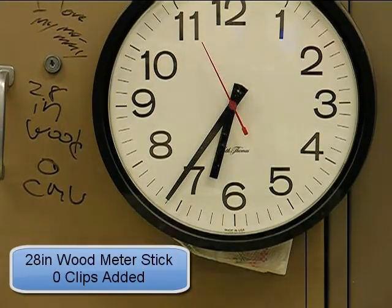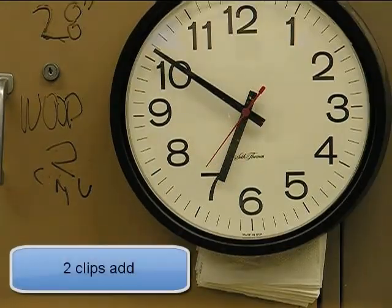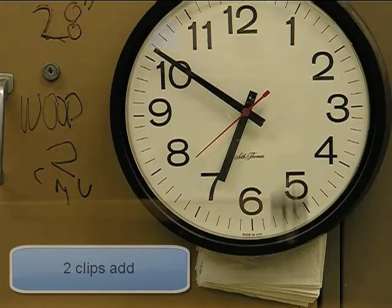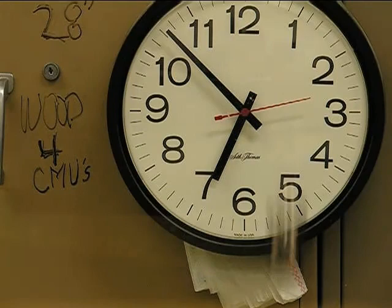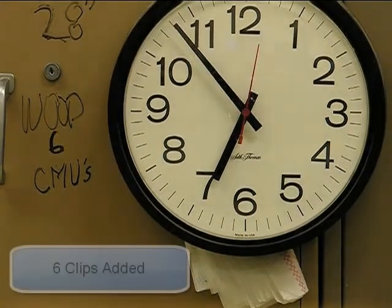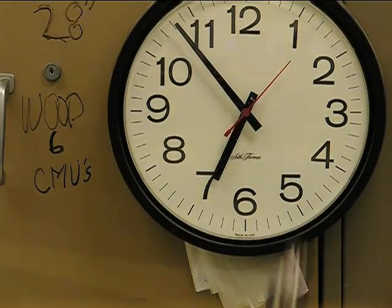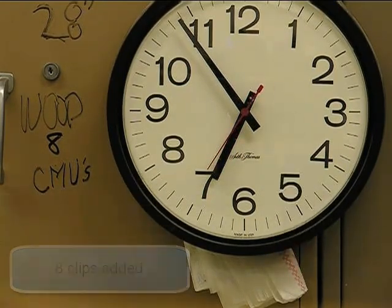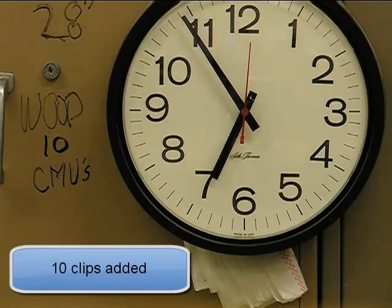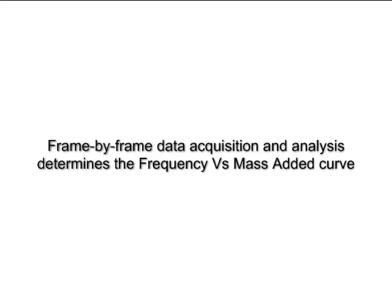So here you have 28 inches of a classical wood meter stick with no mass added. Now we've added 2 clips to it, and you can see that it's moving slower. Then we're adding 4 clips to it, and it's yet again slower. And so we can progress through this and keep adding mass to the end of the cantilever. And you can record the resonant frequency by looking at the frame by frame data. And when you're all done, you can collect all of that data and plot it, so you can do an analysis of frequency versus mass added.